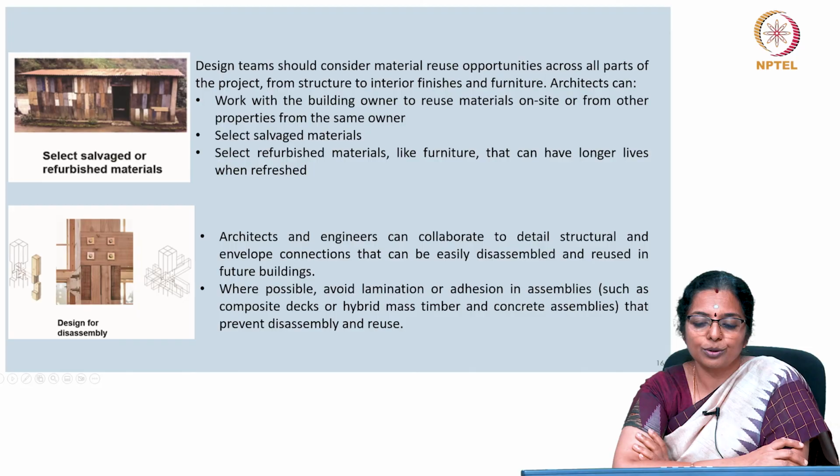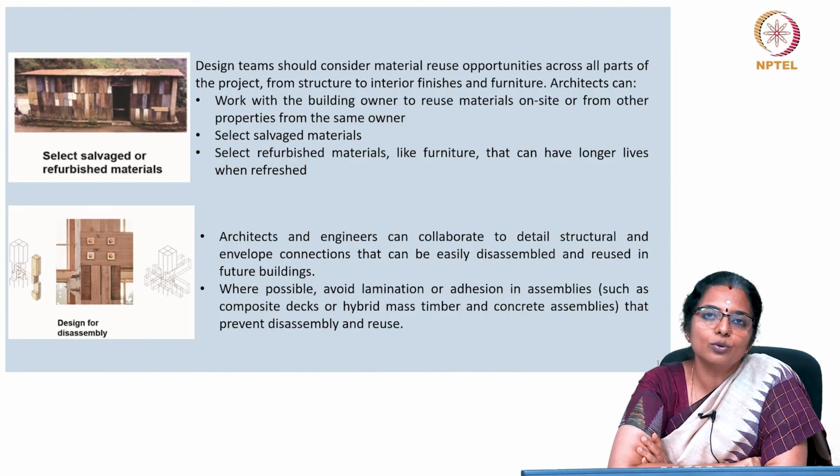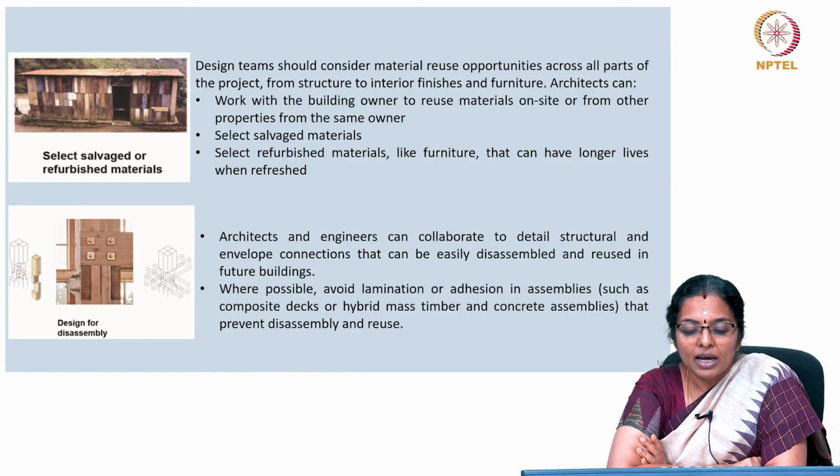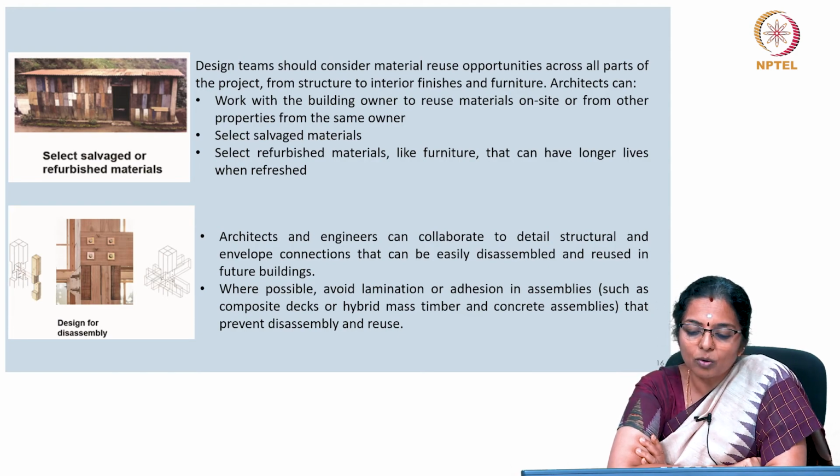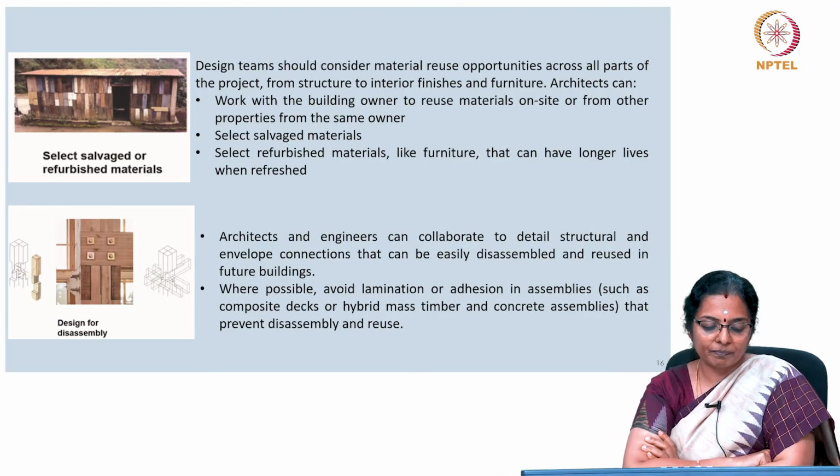Design teams should consider material reuse opportunities. Wherever possible, do not demolish and send the products to landfill. Try to reuse as much as possible. You can work with the building owner to reuse materials on site or from other properties from the same owner. Select salvaged materials. Select refurbished materials like furniture that can have longer lives when refreshed.